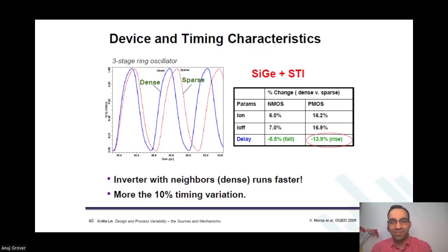Sir, what exactly is this STI? I'm unable to understand this. Shallow trench implant. We discussed shallow trench implant in the second lecture of the DVD, on the manufacturing process. How do you separate two devices from one another? You remember we said we would break open the silicon and make shallow trenches between two devices and deposit oxide. So before shallow trench technology, we would grow silicon dioxide on silicon itself. That led to the beaking effect. Remember?